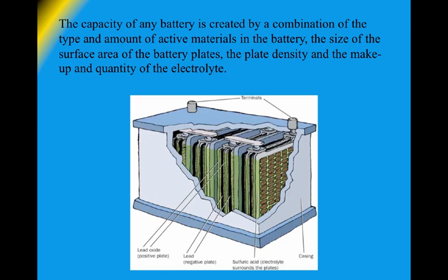For our static photovoltaic and other renewable energy battery storage applications, we want a battery that can be discharged over a long period of time at a less dramatic rate and hold that charge for a long period of time. So the plates are more dense and they are larger and there's more of them.